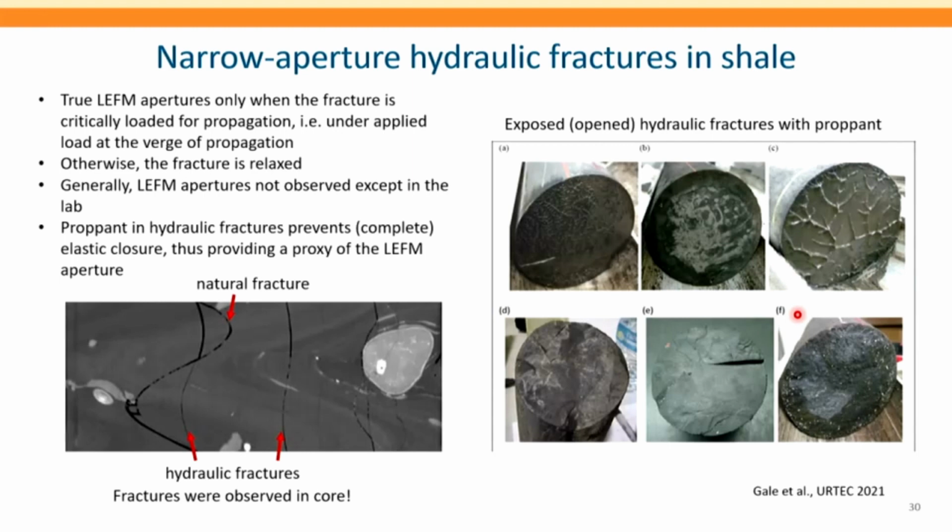Now, going back to the story of aperture size and shape, okay? So this was all subcritical fracture testing, fairly well understood. There's a fair amount of literature on this. We know that fluids can react at the fracture tip. It can weaken the rock, it can strengthen the rock. It has primarily an effect on the velocity of the fracture, which can also affect connectivity in the end. So it's not just how fast it goes, but how fractures interact.